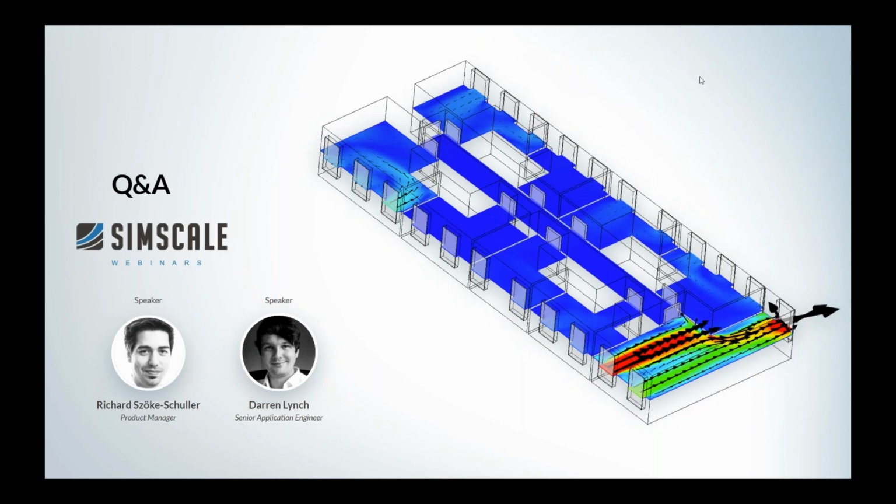What we actually do is we set off the outdoors wind comfort simulation. This creates our pressure coefficient values for us. We programmatically download those pressure results, process them into pressure coefficients, that we then do some additional upscaling on depending on the scenario that we're doing, and we input that manually into the indoors study. But of course, as we've covered in the past quite a lot, we have got the